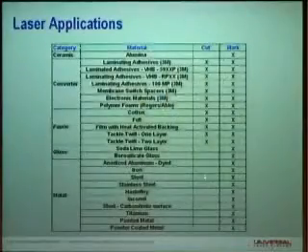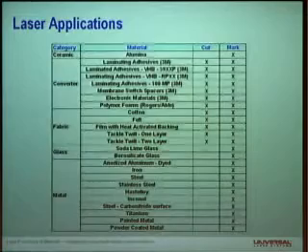Metals, extremely thin iron, steel, and stainless steel, like 1 or 2 thousandths foil we can get through in certain cases. One that's typically done in your lab is aluminized Mylar. You can get through that if you use the laser to heat the Mylar, and then the Mylar in turn heats the aluminum. So there are special cases where you can cut through very thin metals, but I listed cutting with a CO2 laser of the power that we have available as a no. But we can mark all those metals though, either directly or with the laser marking compound.